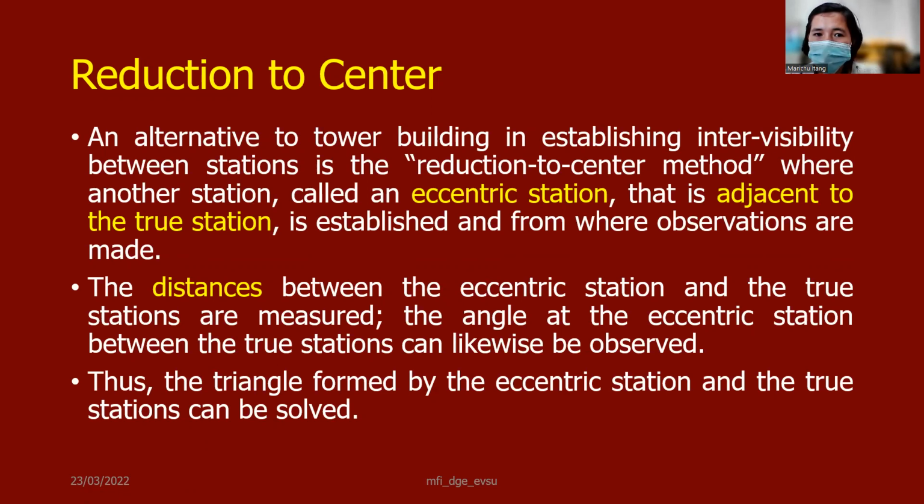So one of the alternatives to the establishment of towers, just to see the stations which are unavailable or not really intervisible, is this one, the reduction to center. So the concept of reduction to center is just you have to establish another point in which you can see the other points with respect to the original point. So you just put an observation point. Okay, so this is an alternative to tower or building in establishing intervisibility of station.